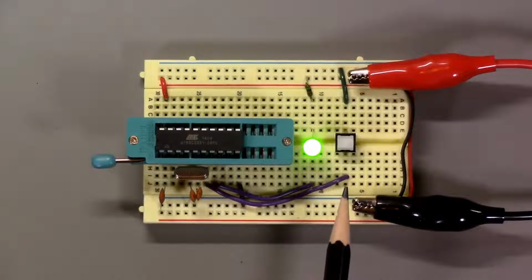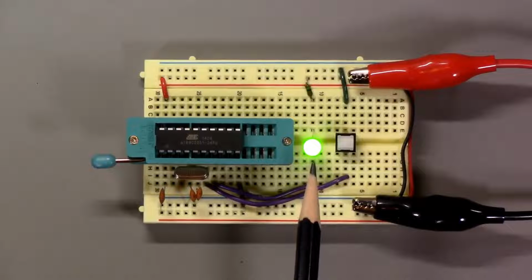And essentially what that seems to indicate is that if there is a transition on an input from 1 to 0, it doesn't seem to automatically switch from 0 back to 1 when the voltage at that node in the circuit is allowed to return to a high level. So the switch is no longer connecting that node of the circuit to ground, and yet the value of that input continues to be read as a low value, and the LED stays on as controlled by the firmware program.